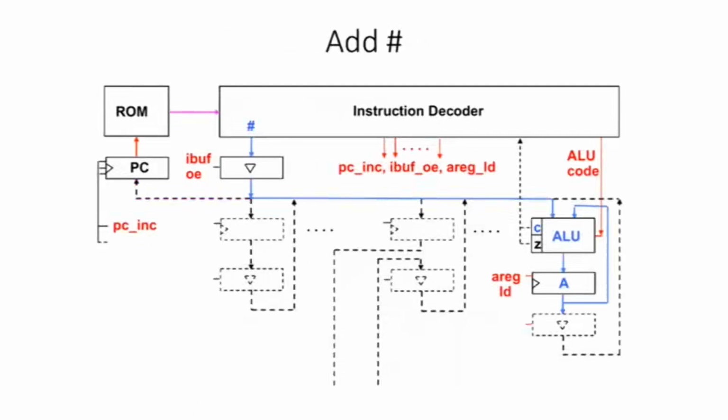Those are flags. The C flag will be 1 when the last addition you did created a carry. So it will remember that the last number that I have put in the accumulator is actually 1 too little because I had a carry at the end. And then we have a Z, and that says the last logic operation you did resulted in 0. And we can use that to do checks in our program.